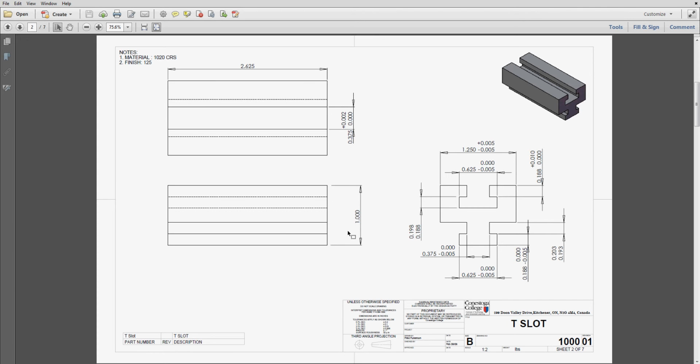I wish to create this part in Mastercam. It's simple line construction. I'm going to start by creating the part in the wrong view, so I can also show you how to correct that if you're wrong. So I'm going to start with the right side view, but I'm going to put it in the top view, and it's a simple fix to move the part around.